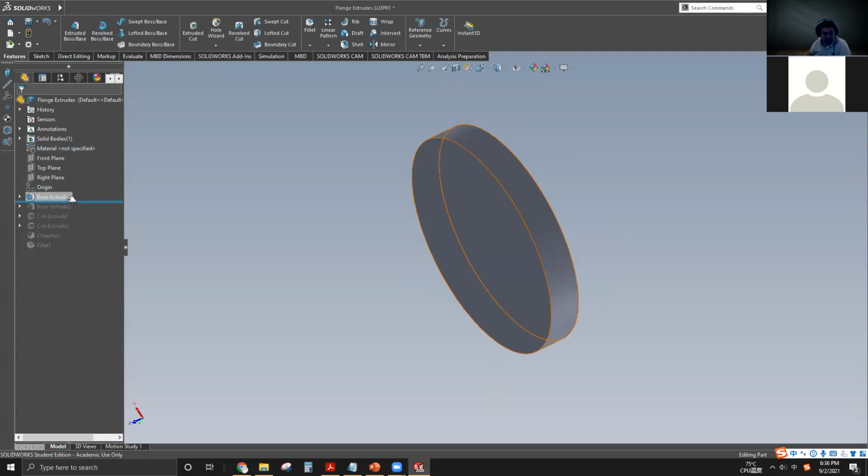And this modeler decided to work off the bottom plate first, which in my opinion might not be the best practice, because sometimes we make the model with a machinist mindset. If you're a machinist trying to make this flange, are you gonna pick a plate like this to work on? How many people would take a plate and use it to make a flange, like what I just showed you?